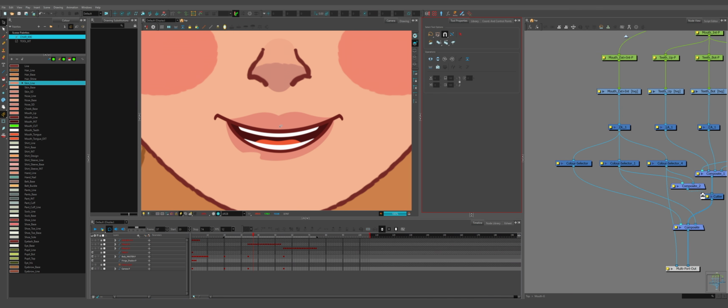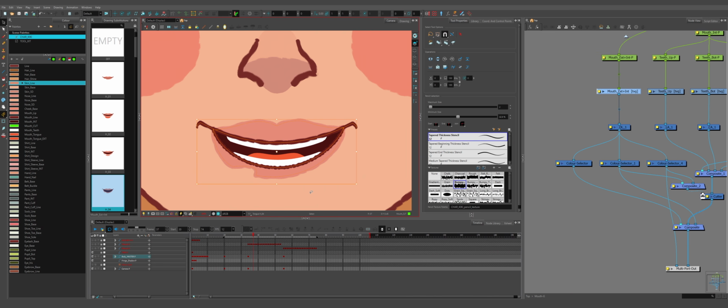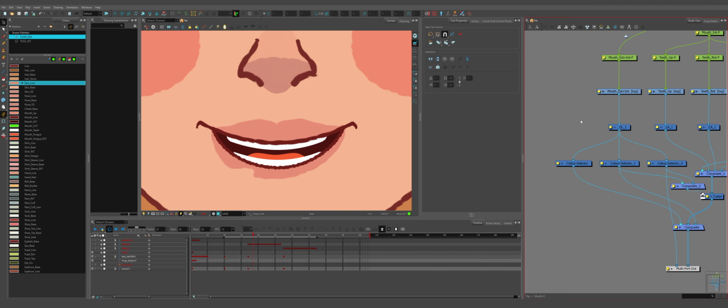One thing I would like to point out with the color selectors is they don't register if you have a texture on your line. So unlike a color override, where you can implant the texture into the color override so it appears, the color selector has no option for that. I don't know if there's a workaround. I haven't been able to find one.